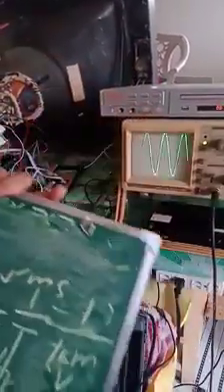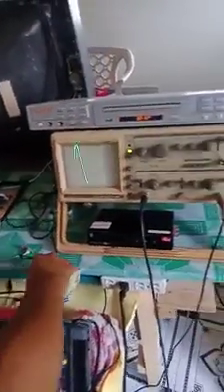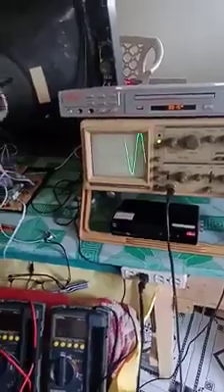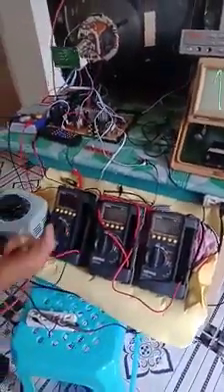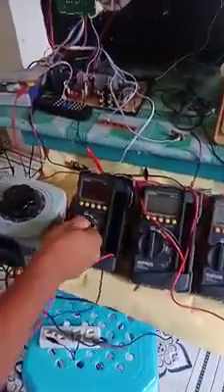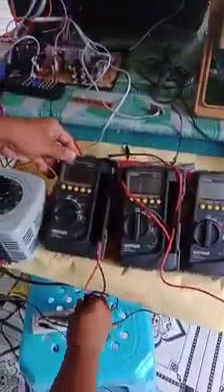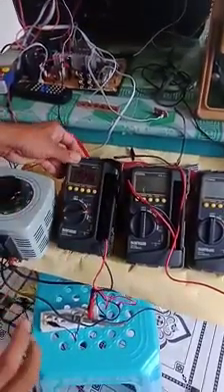It is 60 hertz. So, we can actually measure the frequency of that outlet using also this tester, because this digital multimeter also has a frequency meter. Just set it to hertz. Try to measure. It reads here 59.8 hertz, which is almost 60 hertz.